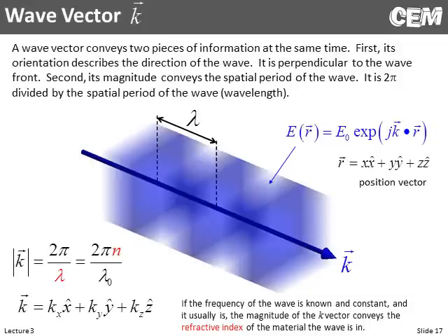The other thing is the notation of just using lambda without the little not subscript. I hate that, and you'll rarely see me use that, because in some cases lambda without any kind of subscript means whatever the wavelength is inside whatever material you're in. Other texts and sources use that as the free space wavelength, and those are two different things.